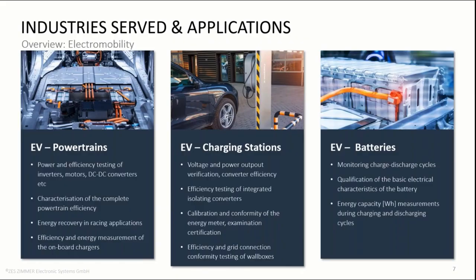Finally, in electric vehicle batteries, or batteries in general, in fact, a power analyzer helps monitor charging cycles and measure some basic electrical properties such as charging voltage and current, energy capacity in watt hours, and charge in ampere hours, as well as internal resistance and thermal joule dissipation, and many more.